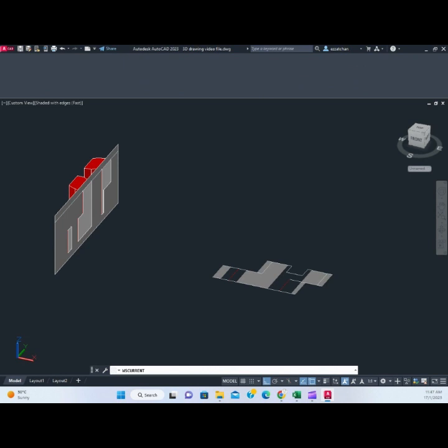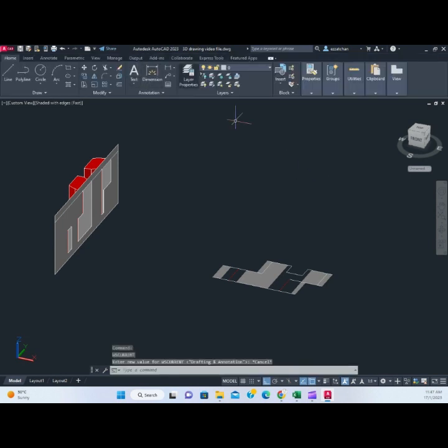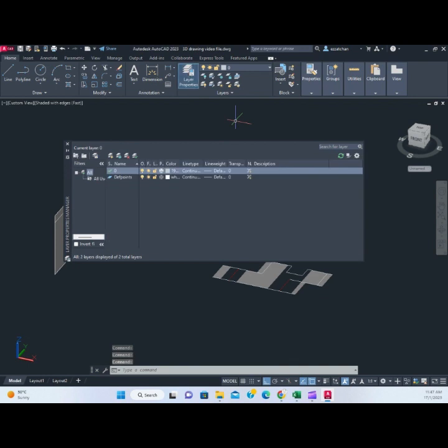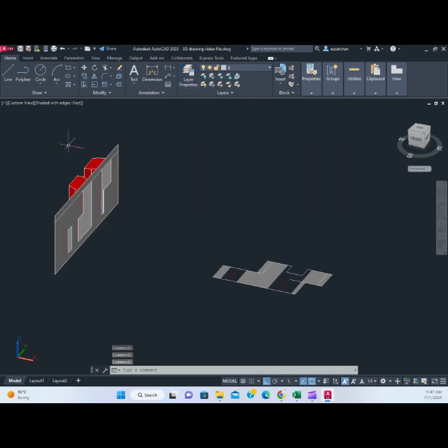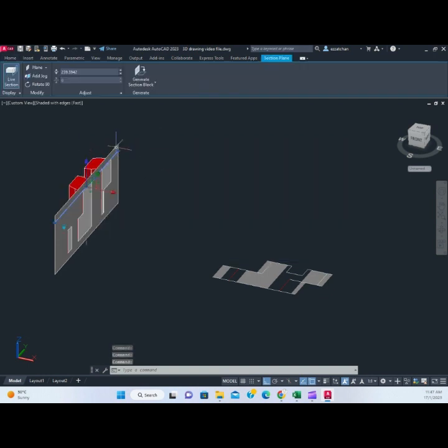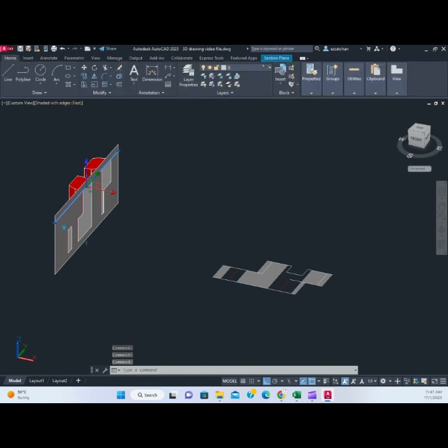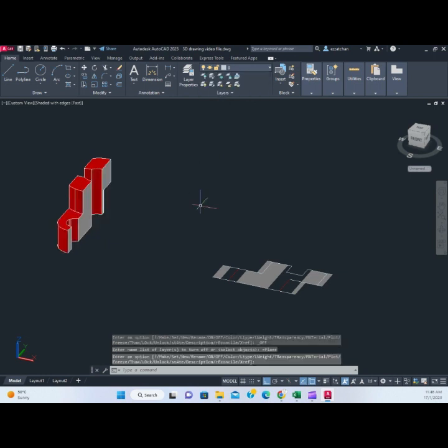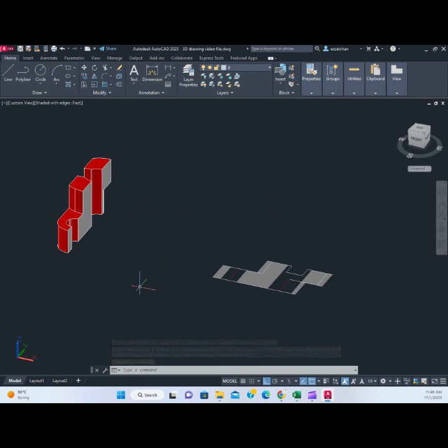Let's say I go back to drafting mode, and I see what layers I have, and let's say I create a layer called plane, so that I move that plane into that layer. So I close this dialog box, select this plane, go back to home and move it to plane. Now if I turn off plane, that whole plane is removed from our view.